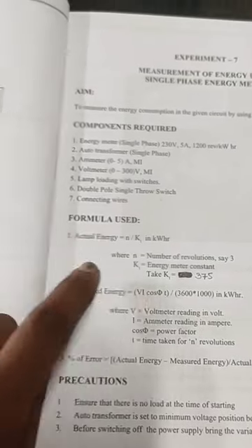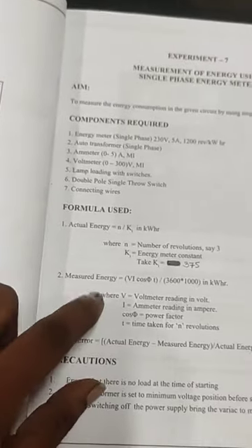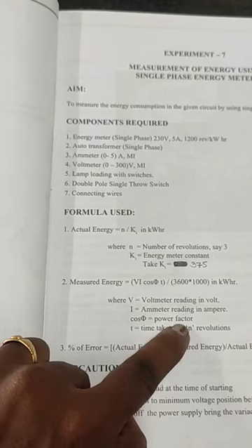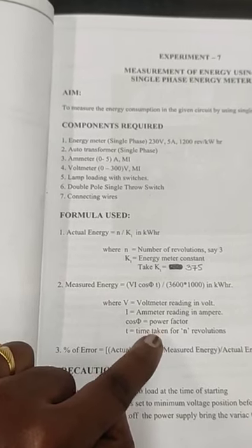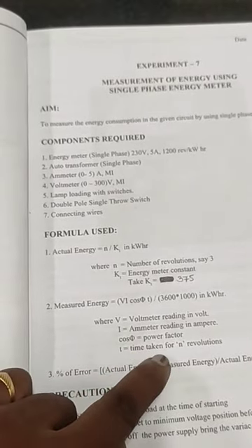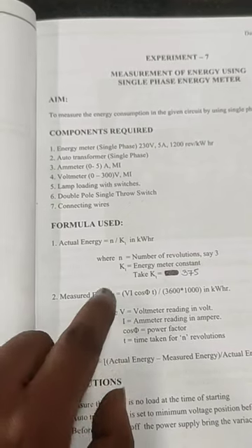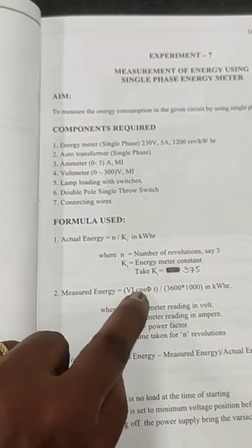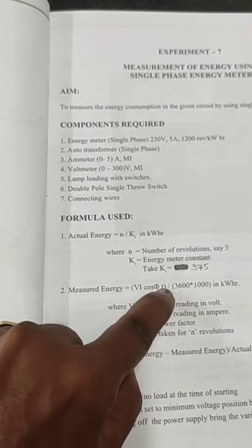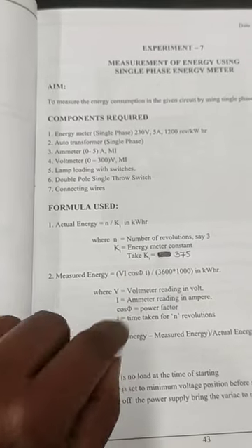V and I can be taken from the voltmeter and ammeter values. Cos phi is another name for the power factor value, and we are using 0.8 as a constant power factor value, where T is the time taken. So when the time is included, this is the energy value. VI cos phi is generally a power value. Here we introduce a time period so that the power is termed as the energy consumption rate.